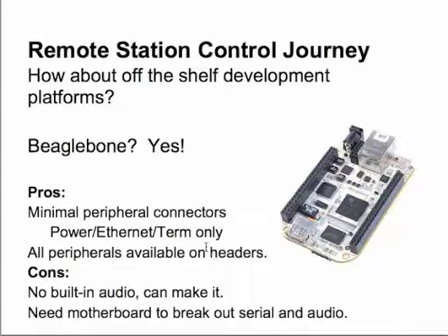The BeagleBone is very similar to the BeagleBoard, except it has minimal connectors on it. So we have Ethernet and power back here, and we have a USB host connector here. There's a SD card here, which is actually the operating system for the device. And also, what you can't see in the picture, there's a USB connector on the other side of the board on top that's the shell, the Linux terminal. So if you wanted to log into it and actually get to a command prompt. It doesn't have built-in audio though, but it can be made.